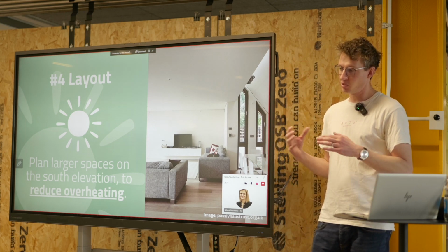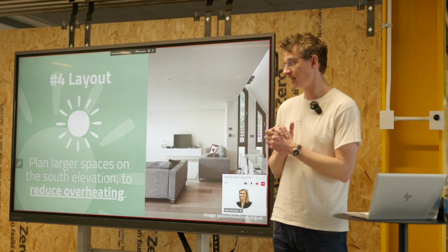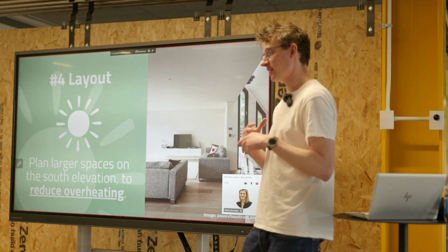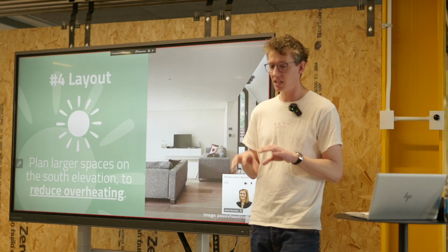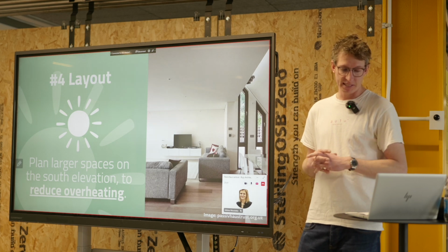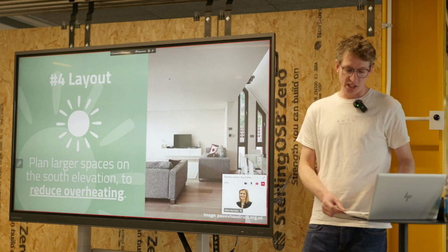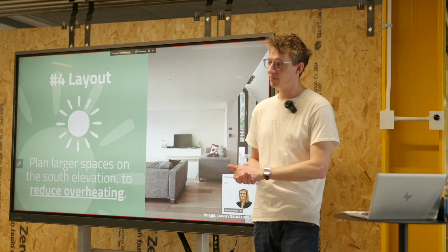You can't really shoehorn these things in at a later stage. It's better to get ahead of the game with these things. And even if you're not necessarily designing the whole system, you need to allow the space for it. And you need to be thinking, how can I service those rooms by having a centralised plant room. An MVHR unit, if you're not aware, stands for mechanical vent heat recovery.